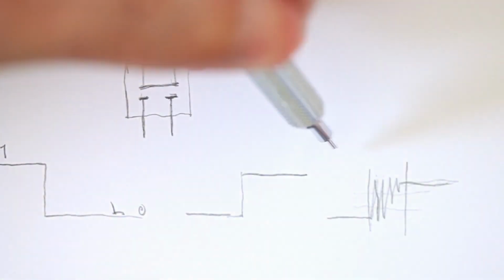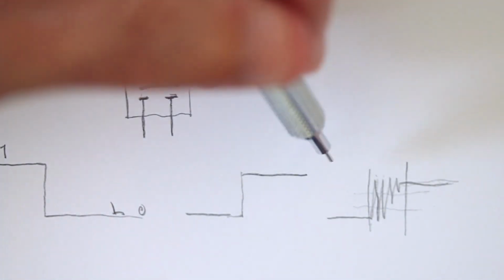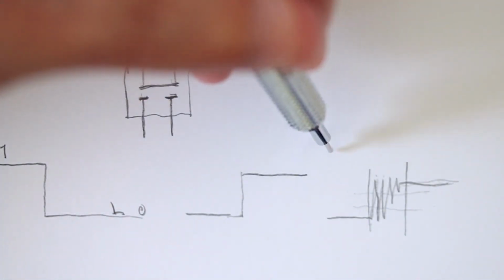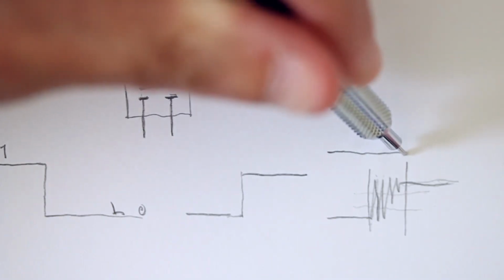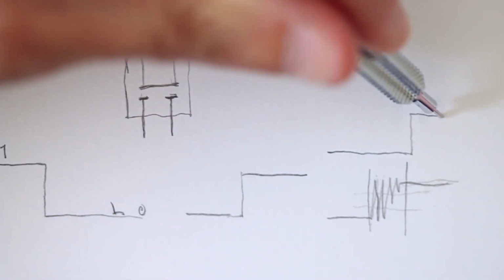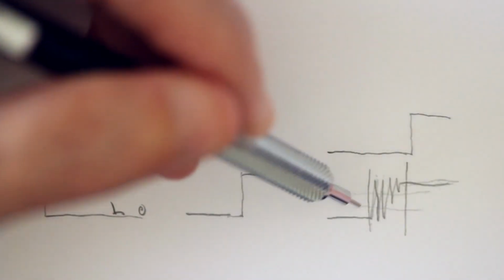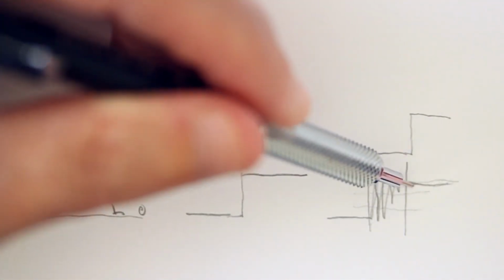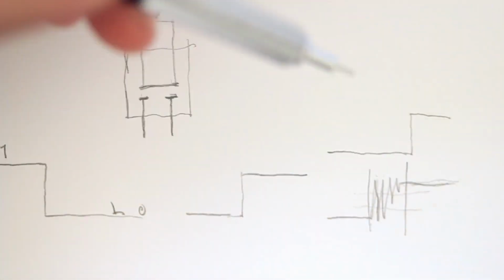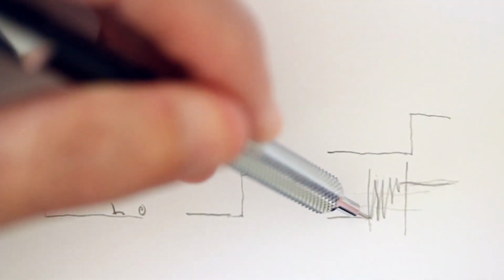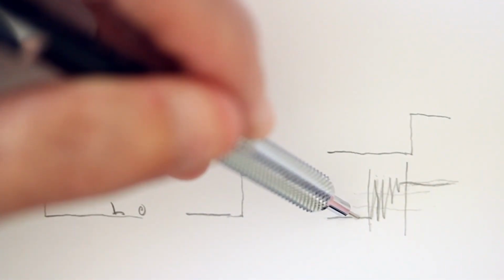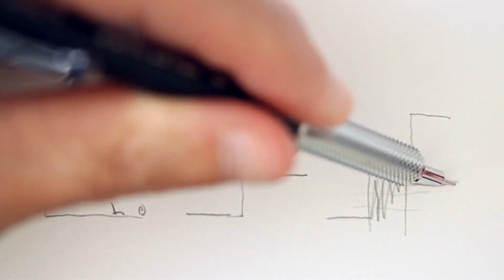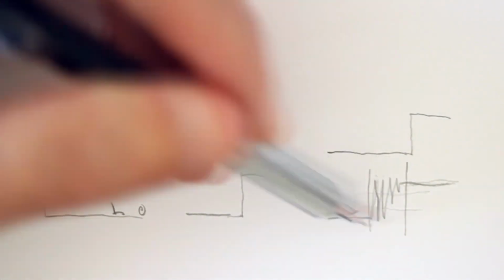So when the LED is toggling, it's going from off to on. Let's say it starts off. We don't want it to turn on until it passes this threshold here. I'm going to use a counter to count cycles when this is actually constantly a high or low signal. I'll count it on a low signal and I'll count it on a high signal, so we'll know if it's not being pressed and if it's being pressed. All this stuff will be eliminated in software.